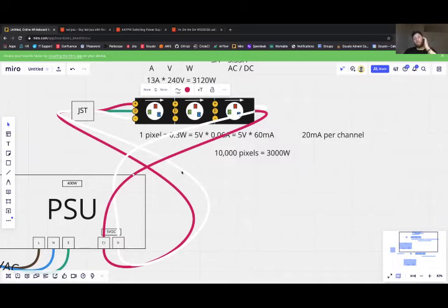So you actually want to inject power both at the beginning and the end of your strip. Now, once again, since these are in parallel, you're not even really dependent on these power inputs here. You can inject the power wherever you want. It's completely agnostic to the location of the power injection from the perspective of crafting a valid circuit. From the perspective of voltage drop, you want sufficient power inputs into your LED strip in order to ensure the voltage drop doesn't occur.